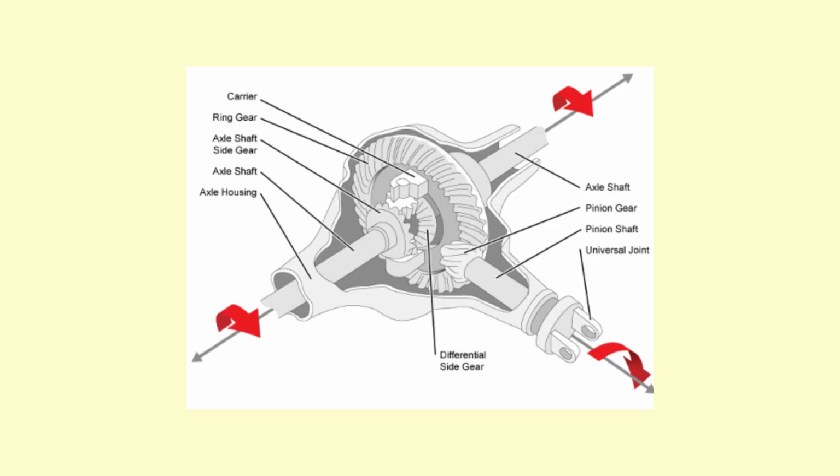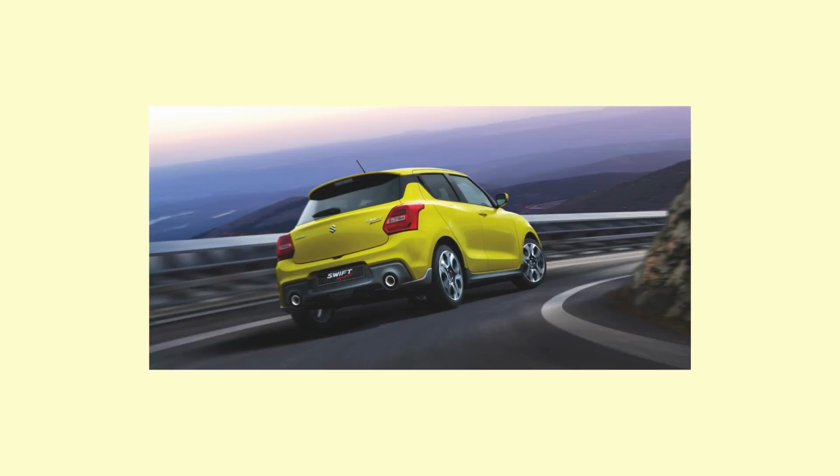Before we get into why an LSD is a highly lauded handling mod, let's explain the open differential, installed in the vast majority of cars today. When one wheel loses traction or slips, it will spin freely, whilst the other wheel that has more grip receives less power. During turning, the inside wheel usually spins freely, resulting in nasty understeer due to imbalance in grip.